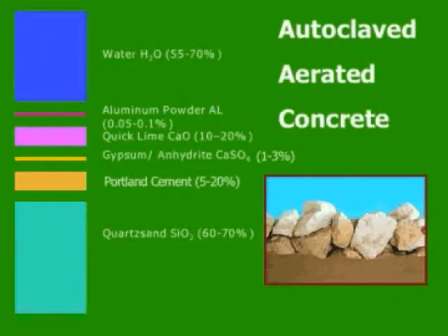The percentage used of each raw material is not just a guess. AAC is produced in several different compressive strengths. As more H2O is introduced, we produce a lighter material and we increase the R value. However, we decrease structural values and decrease the sound value. But if we use more quartz sand, for example increase the volume to 70%, we increase the structural value and increase the sound value. However, we decrease the steady state R value.